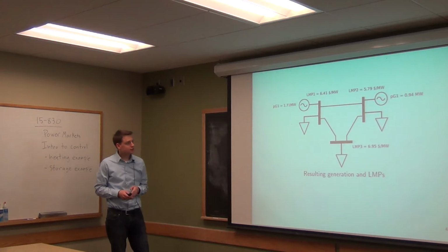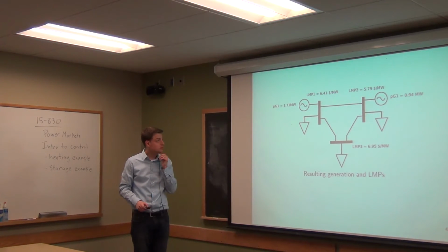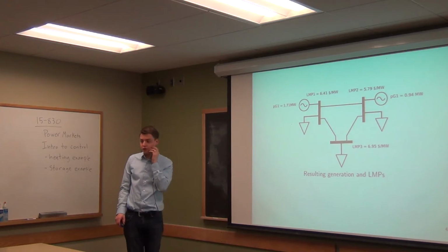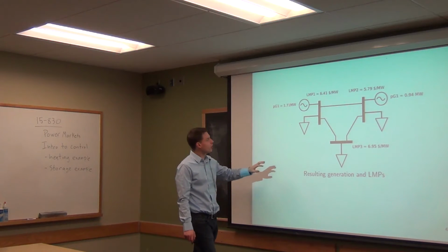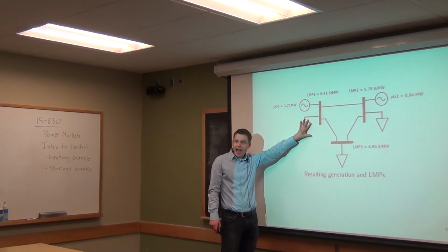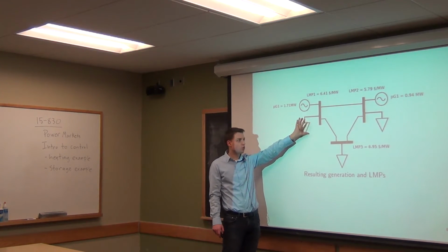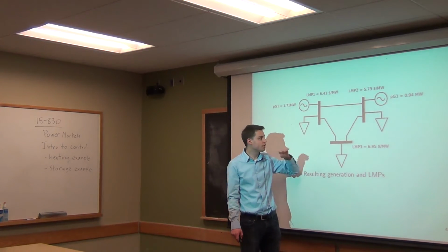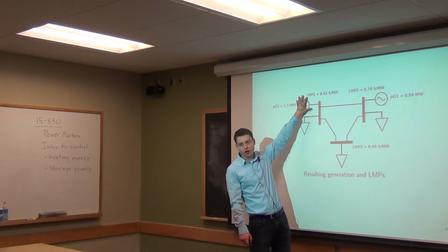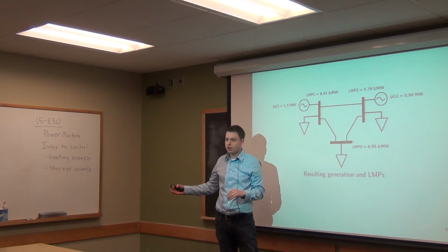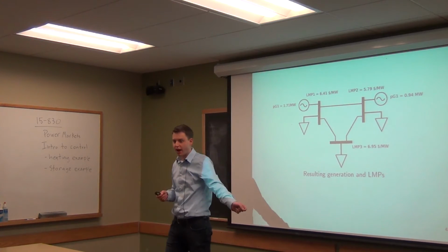Yeah? So for the other two nodes, it just supplies the power directly. It has no power flow? No, there is power flow between these two. What you'll notice is that this one might be generating it all. If there is a load at this node, and in this case it probably would in fact be generating it all here. If there is a load and generator at the same node, and the generator does not hit its maximum amount, then you will always just use that power to provide your current load too.